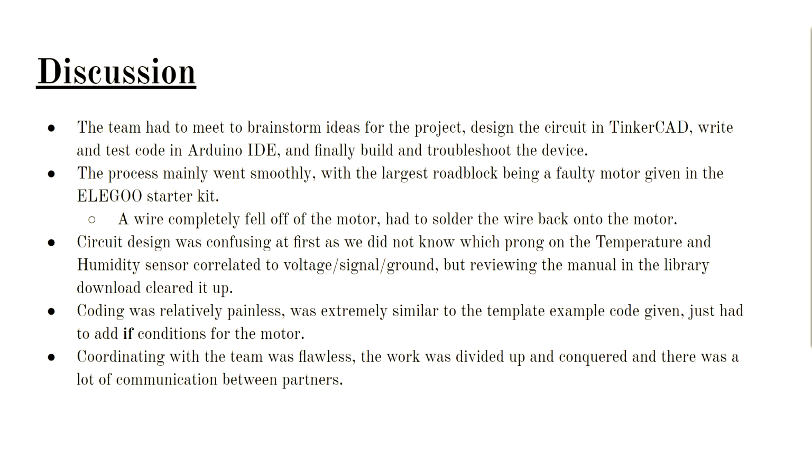On to the discussion. Our team had to meet to brainstorm ideas for the project, design our circuit in Tinkercad, write and test code in Arduino IDE, and finally build and troubleshoot the device. The process went along smoothly, with the largest roadblock coming from a faulty motor provided in the ELEGOO starter kit. A wire had completely disconnected from the motor, so it had to be soldered back on in order to continue our challenge. The circuit design was a little confusing at first, as we were unsure which prong on the temperature and humidity sensor corresponded to the voltage signal. But after reviewing the manual in the library download, it cleared things up.